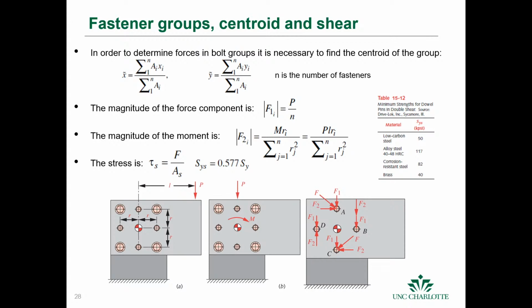And if you're designing a clamped joint, you'll design it to have those clamping forces from the bolts. The dowels are there for accurate locating and to help prevent shear. Okay, but they don't help you with the clamping force. So I hope that answers your question.